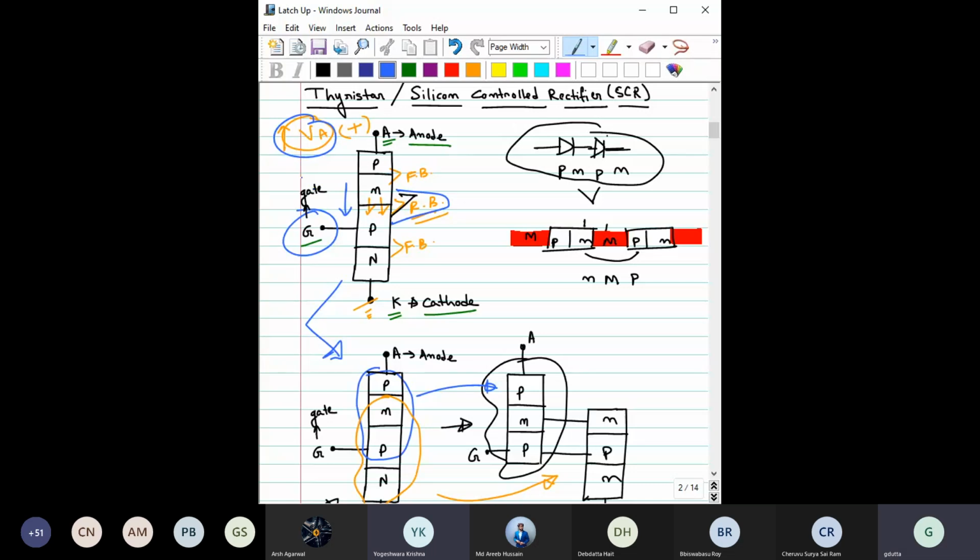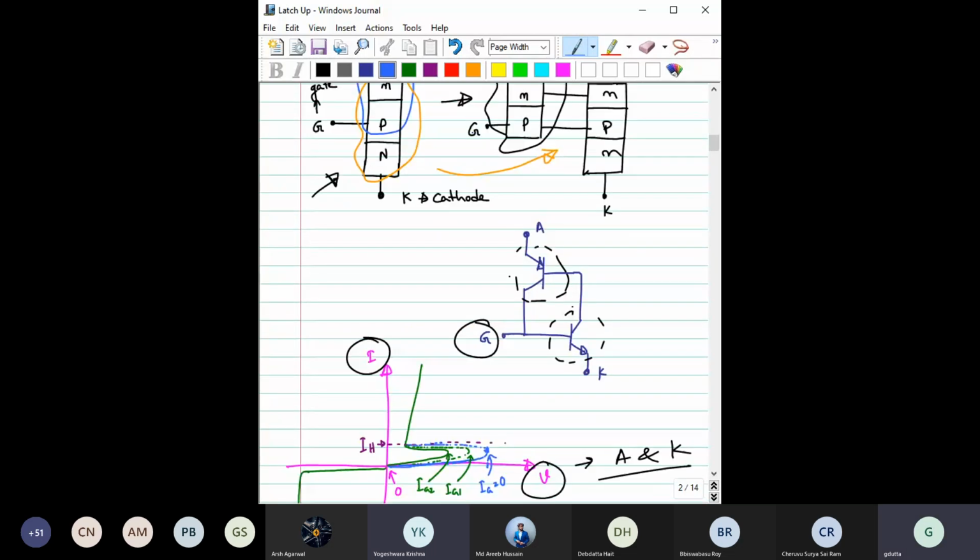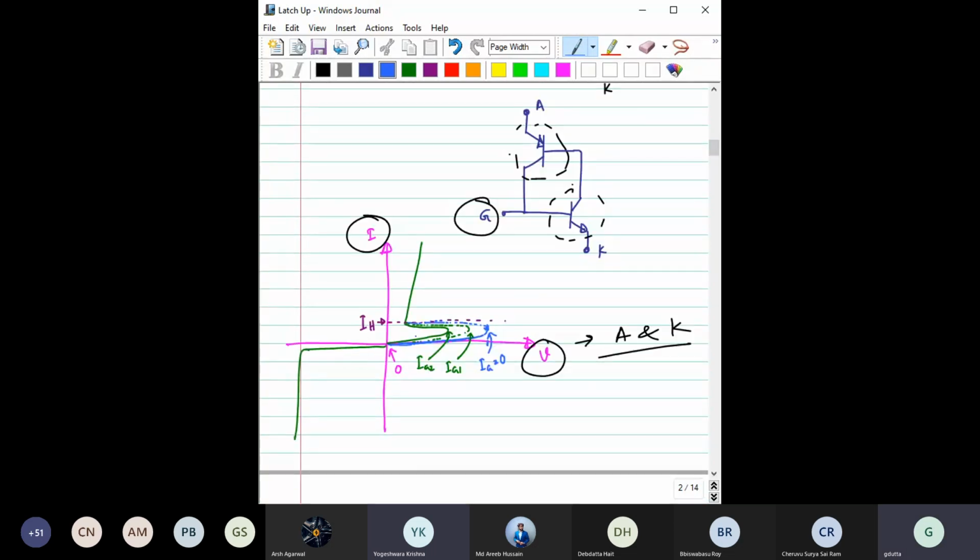For example, when you have a diode operating in breakdown, what is the resistance across that diode? It is basically a type of short, so there is a very small voltage drop across this diode. Then what will happen to the voltage between this cathode and anode? That voltage also has to drop, because you need only this junction to be forward biased. The voltage across this diode is significantly low. Then all of a sudden the voltage that you have applied will drop to this much.